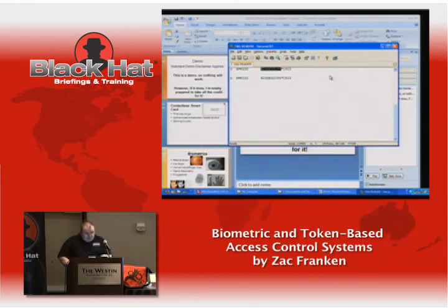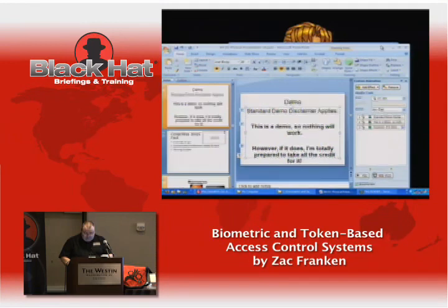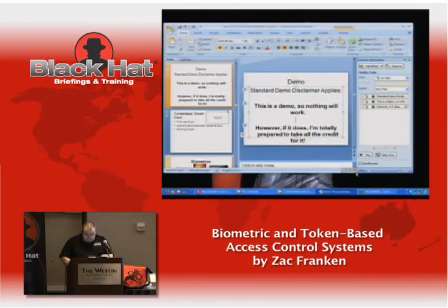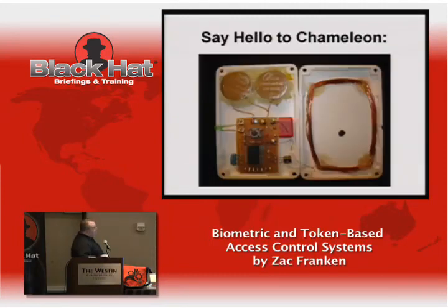Let me just flip back to our slides here. Basically, we have a coil of wire and a capacitor, which forms a resonant circuit. This oscillates nicely at 125 kilohertz, which is the field put out by this reader.